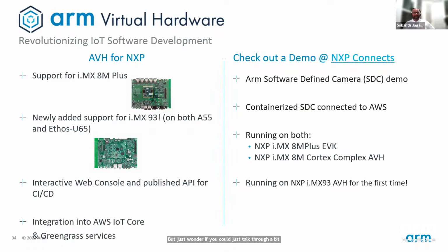Sure. From a software perspective, we have the Linux kernel supported. Every quarter we have our Linux BSP released from NXP, and the i.MX 93 has been included from the end-of-Q1 Linux release. That's for the A55 side. On the M33 side, we also provide RTOS support.